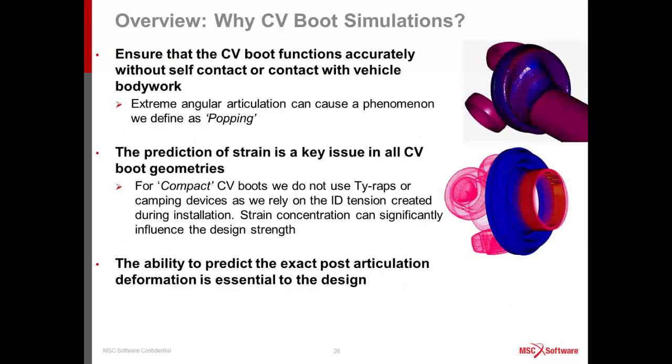We look at these type of simulations because we want to ensure that there is no self-contact as much as possible within the boot, which is likely to cause heat build-up, and there's actually no contact with the vehicle body or any of the bodywork around the boot area. Extreme angular articulation can cause a phenomenon that we call popping, which is when the CV boot actually comes away from the shaft and starts to fold out on itself. This can be caused by grease loading or lack of contact forces on the shaft.